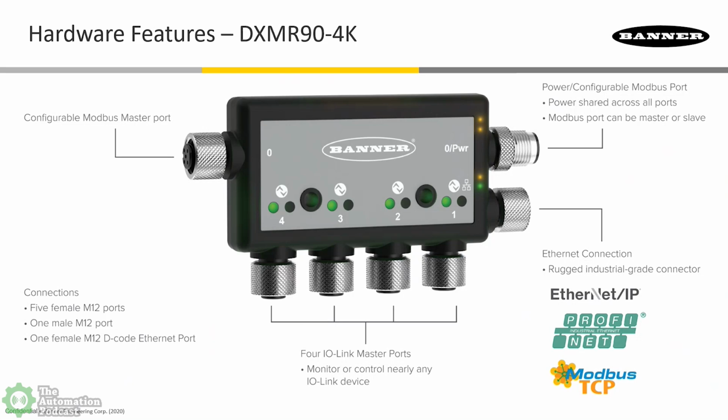On the left side of that IO-Link master in this image, there's a Modbus RTU port, and that's been a real unique feature of this IO-Link master. You can add things like condition monitoring that you want to send back to your control system. Maybe you want to add vibration sensors. Use some of our existing converters to convert things over and connect them to your Modbus port: vibration, temperature, humidity. It enables us to do a lot of interesting things with that Modbus port and also add a lot of devices. So with Modbus, you could tee into lots of devices on your Modbus network and bring it back to your control system. Absolutely.